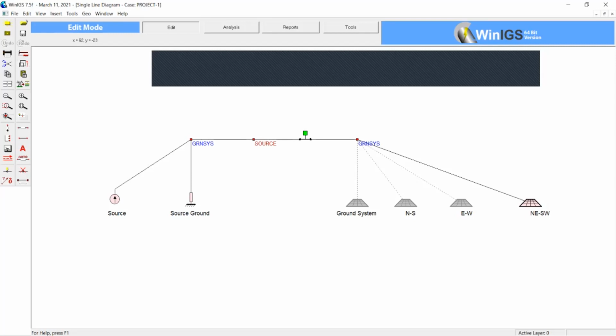Now all the top layer soil resistivity for 3 models you add up together and divide by 3. Same thing you have to do with the bottom layer soil resistivity. You add 3 numbers from 3 different models and divide by 3, and the height also. That will be the average value.